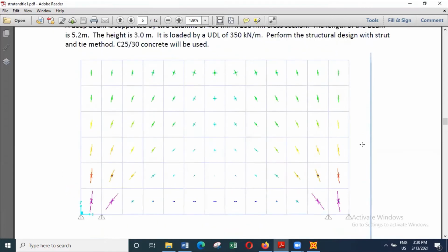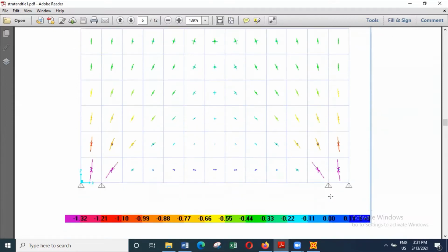Once you run a FEM with plate elements, we can get an idea about the load transfer. Once we get an idea about the load transfer, we have to work out an equivalent model so that we can maintain reasonably close angles for these struts. Otherwise, we have no guidance to see what the angle of the strut is. But once you run a FEM model, you can clearly see the angle that you have to use for the strut. Any question on this?